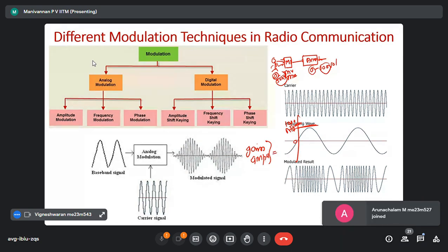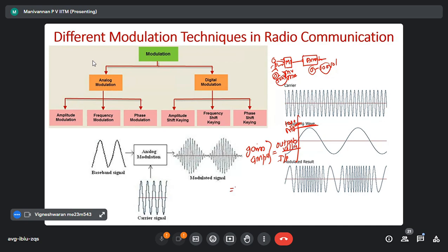Okay, gain of the amplifier is nothing but the output voltage of the amplifier divided by the input voltage. I said we take maximum output of only 100 volts. 100 volts is nothing but 1 lakh millivolts, divided by 500 input millivolts. So what will happen? This I will say 2, and this 0 will go. The gain of this amplifier is nothing but 200. It is going to 200 times. So the amplifier is going to amplify 200 times. It takes an input electrical signal and gives again an electrical signal, which is given to the speaker.